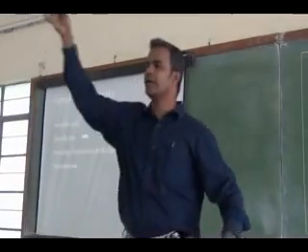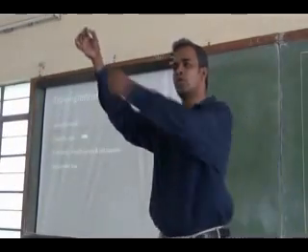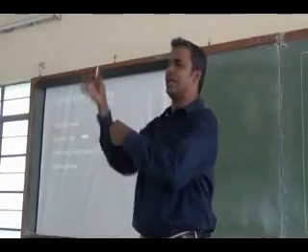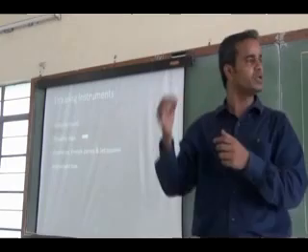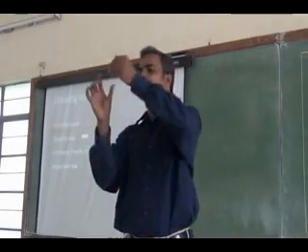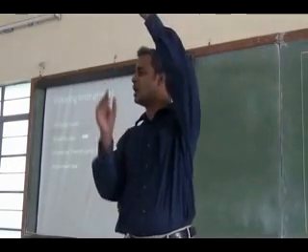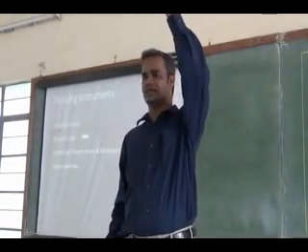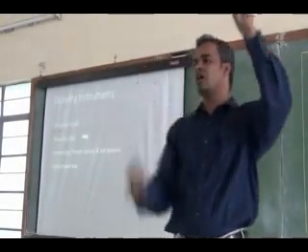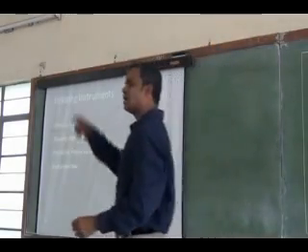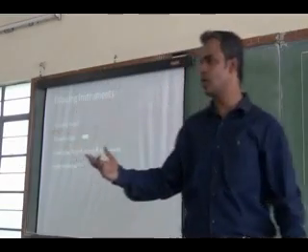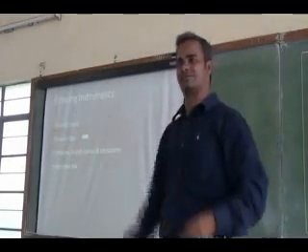This one I can attach to my large compass by removing the pencil portion, and this one I can attach to my bow compass. So the two ends of the large compass and bow compass will be sharp metal pointers that can be used for dividing purpose. That is termed a divider. If I don't have the pencil leg, then it will be a divider.